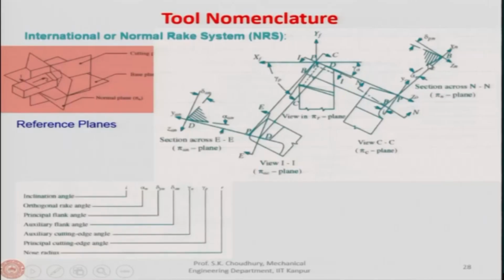So, this inclination we are saying as the inclination of the rake face in here and in here. So, they are different, inclinations are different. Therefore, the angle which is between the rake face and the line perpendicular to the cutting velocity vector, it is here this line in this case and this line in the case of the NN, these two angles.